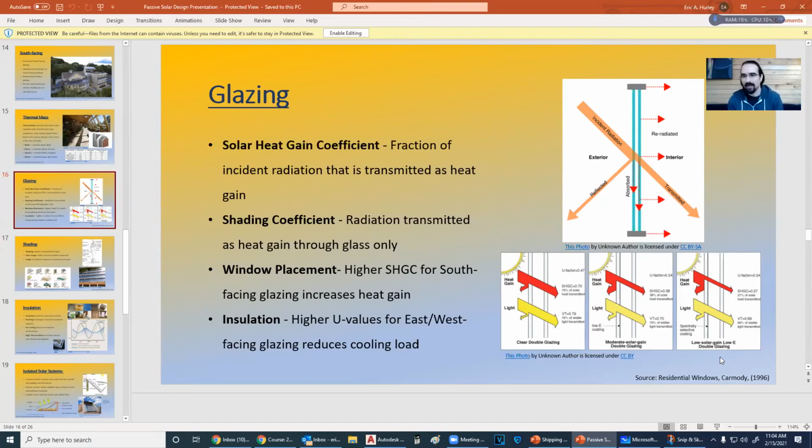I feel that it's probably okay to still continue to ask for those to be low emissivity, and that you can account for the difference in heat gain by adding glazing where you want to and where you can. Unless you're in a situation where you really are trying to capture every single little bit of heat that you can, and not use any extra heat source.